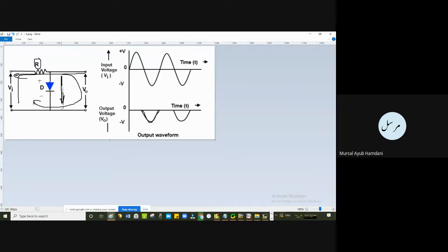In the shunt case, only when the diode is open circuit will the output follow the input. Now when will that come about? When we have reverse bias, negative here, positive here. So you can see it is open circuit, which means nothing from this terminal to ground. However, this input will go to the output rather than going to ground.